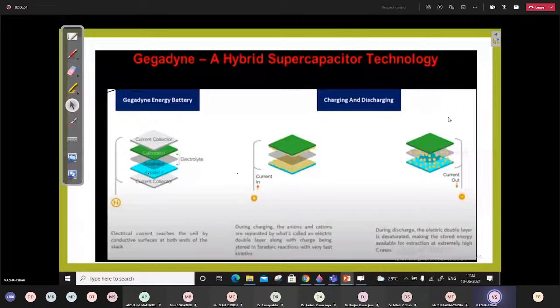This is a DC to AC converter that will provide power to the AC side. Both are bidirectional. So power flows in this direction during deceleration and braking operation of the vehicle, and in this direction during acceleration and constant speed operation of the vehicle.